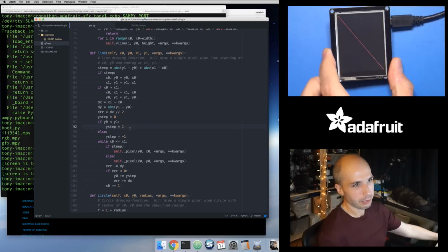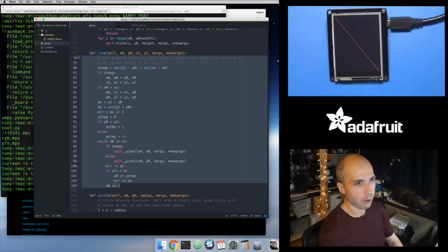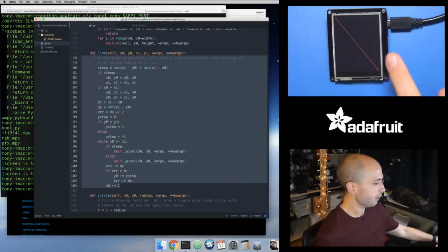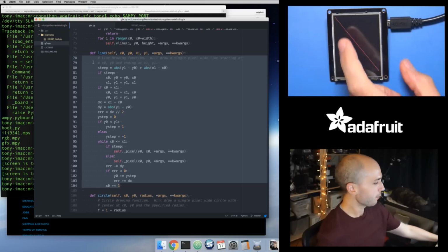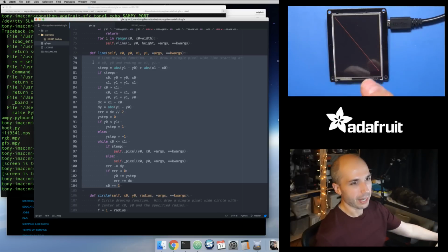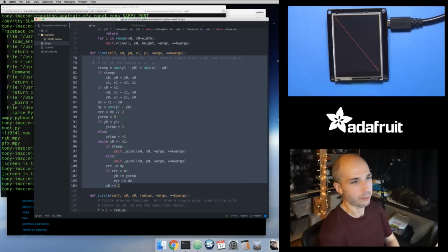Whereas when you have this 320 by 240 size display, okay, now you've got a lot of data to push, and so maybe the Python implementation isn't fast enough. So in the future, we might look at a C implementation of this, where this code is in C and maybe draws against a frame buffer in memory that you can then blast out to this display really quickly. But maybe if you're doing something slow, if you're just drawing like, here's the current temperature sensor state, like draw a red circle if it's high and a green circle if it's good and okay. Who cares how fast it draws?